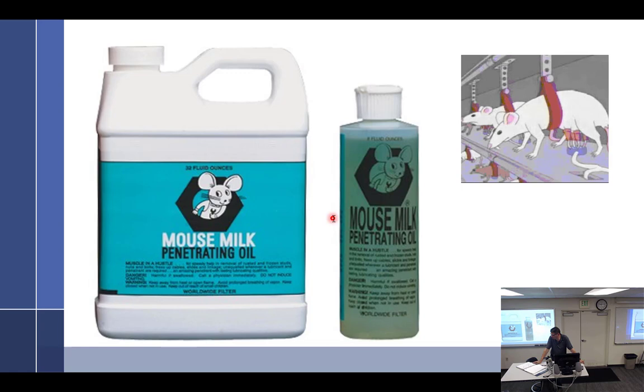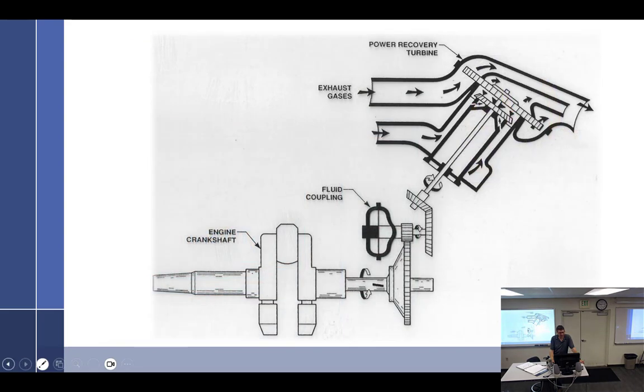We talked about the V-band clamps. We talked about pressurization, which comes off the turbocharger. What's that item where the pressurization comes off the system and goes into the cabin? Oh, the sonic venturi. The sonic venturi limits the amount of pressurization that can be stolen.